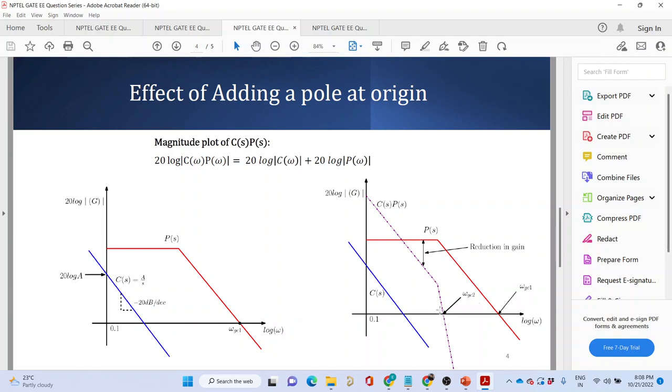One way is to look at the bandwidth itself. A simple way to say it is that the bandwidth has reduced. But if I ask you, if the bandwidth has reduced, so what? What is the problem if bandwidth has reduced? The main thing is you are reducing the gain for this range of frequencies. And this range of frequencies, the mid frequency region, was responsible for making your system fast, because these are the ones which create the fast overshoot, and you have reduced that.